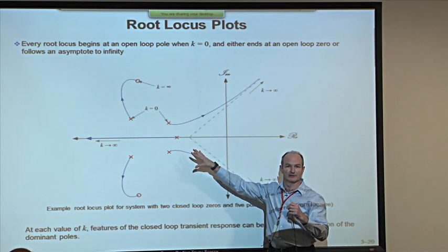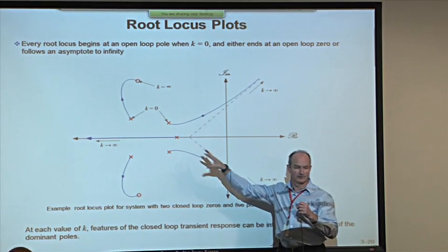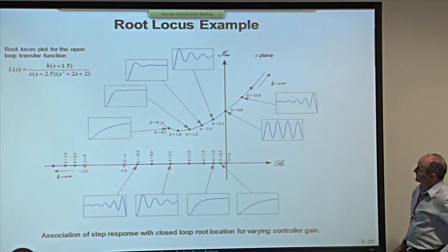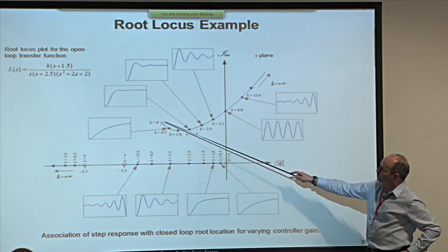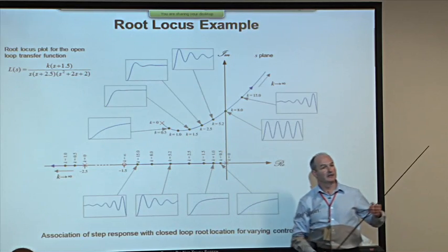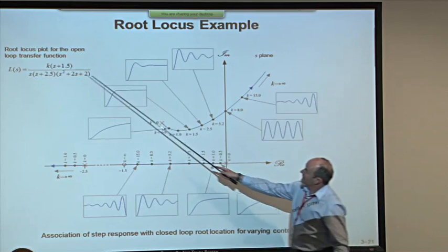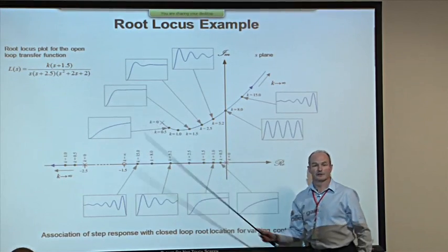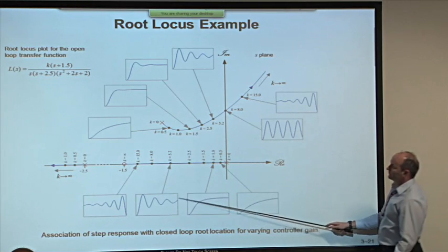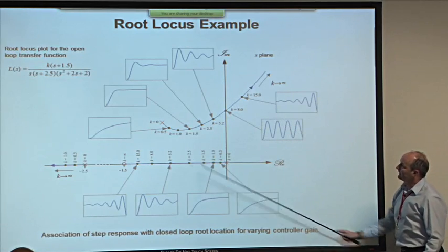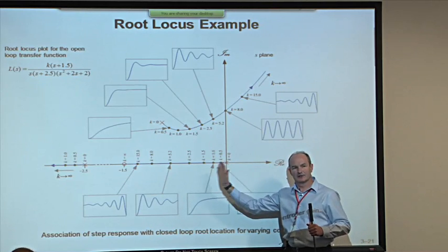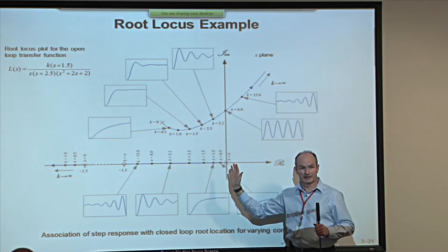We divide these up into pairs of complex conjugate poles. For example, here's a system which has a complex conjugate pole pair, open loop poles. There's one integrator in the open loop, one real zero, one real pole. So the relative degree is 3. It's 3 because we have 1 zero and 4 poles. 4 minus 1 is 3, so we must have 3 high-gain asymptotes. There's one, there's another one, and if I draw on the other side, well, it'd be symmetrical, so there'd be another one down there. Now, the response that we get, because poles closest to the imaginary axis take longest to decay, right?